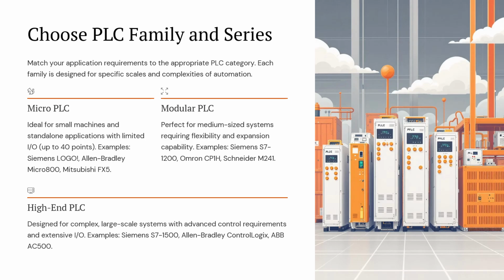Also here, we have to understand the scan time for the micro PLC, modular PLC and high-end PLC. Here we can also consider how many PID blocks there are, how many control modules we have to program, how many equipment modules we have to program. So based on the scan time and program memory, we can select the micro PLC, modular PLC or high-end PLC.